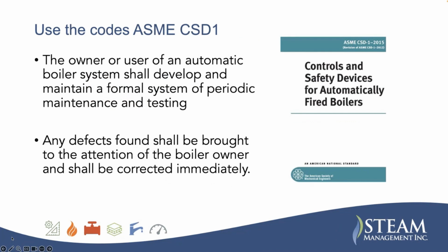Ray: That's why I love it. Sorry to interrupt. What maintenance activity do you think is the most crucial for avoiding an accident? There's a lot of maintenance activities going on, but what do you think is neglected the most that could cause an accident? Well, I think the low water cutoff, that's the leading mechanical cause of boiler failures. And it should be checked and it should be opened up and looked at and inspected yearly. People just don't do it anymore.